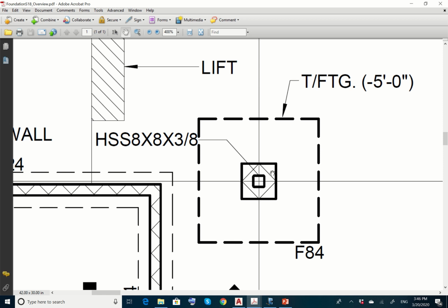And then there is kind of an isolation. It isolates the column foundation from the floor, because there is a floor, okay? So there is this isolation. The detail, how much is this distance, we're going to see that. We're going to know how much this is, and then there is another thickness over here that depends on this, and then this is resting on a footing. So this dotted line is the footing.